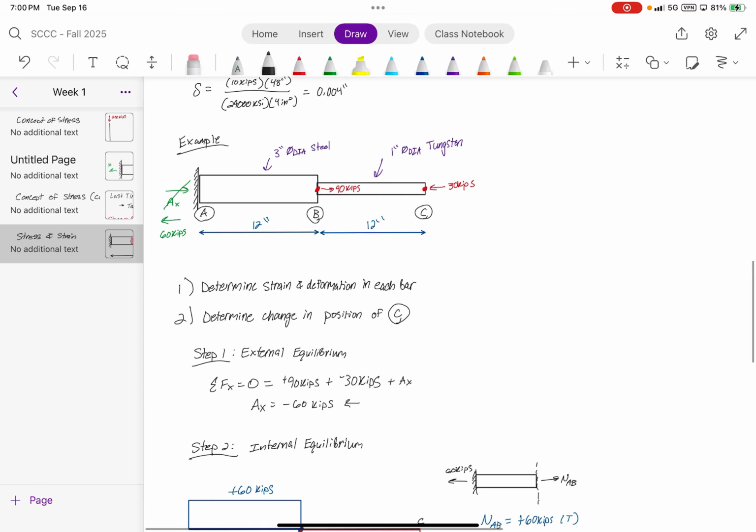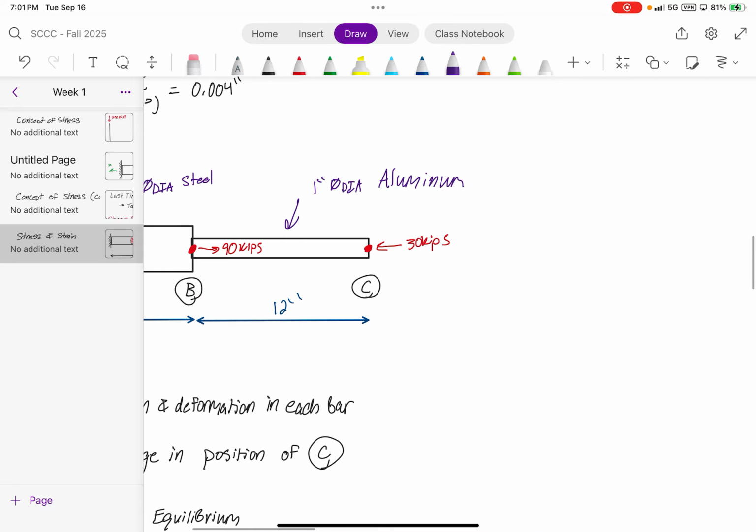Change. All right. Let's do some aluminum. Yeah, I was just thinking that. You read my mind. So let's change this to be aluminum, but we got to pick an alloy, right? Because different alloys have different moduli of elasticity. So I'm going to say, just do a combo. Make it easy for everyone. Alloy 7075 T6.